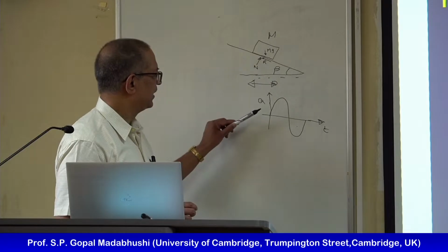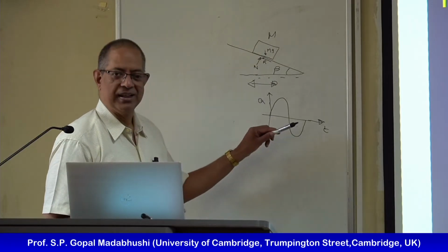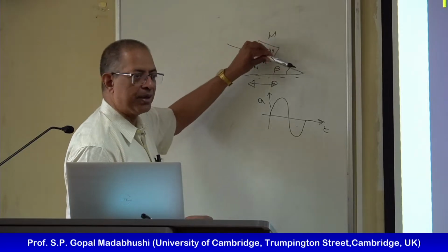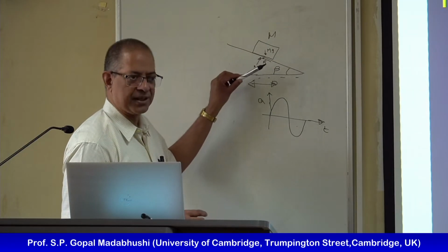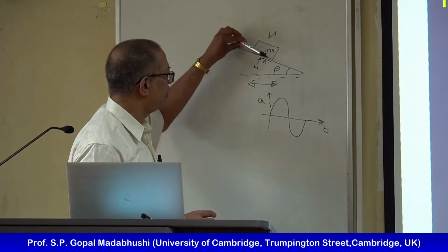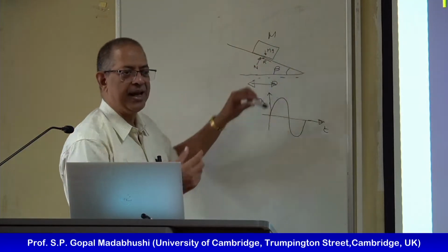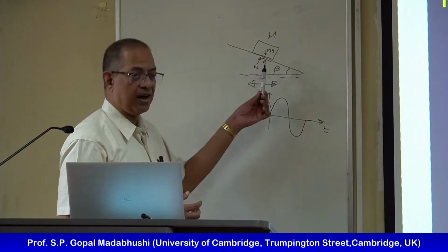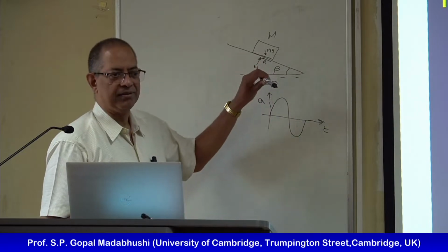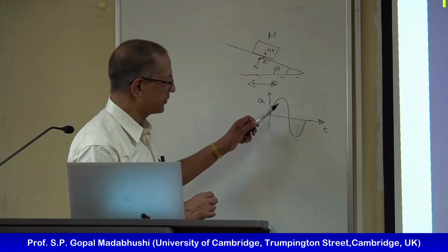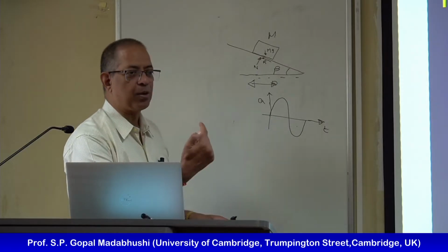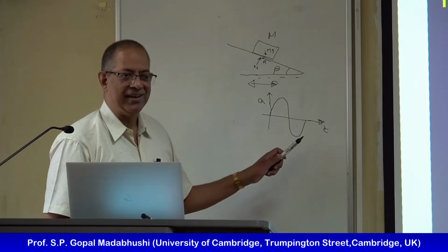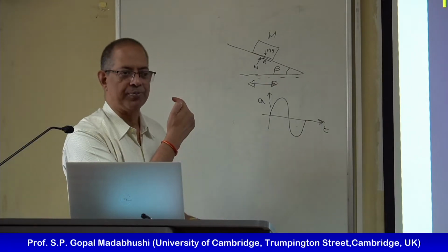If I shake this strong, I'll have the block which wants to slide down, but it's being held by the resistance force. If my downward acceleration times mass, if that force is bigger than r, then it will slide, right? In that first positive cycle. But in the negative cycle, the block is being accelerated up slope. If my pulse is big, it can also slide up slope, right?